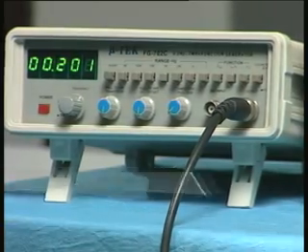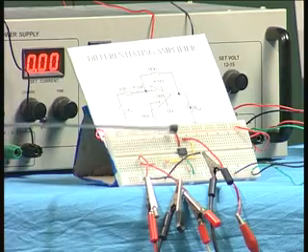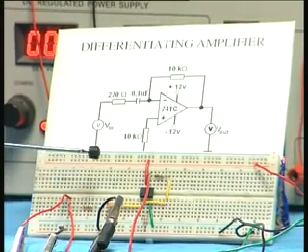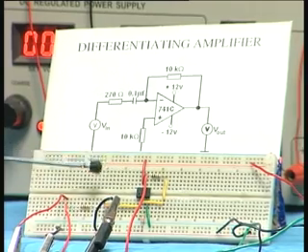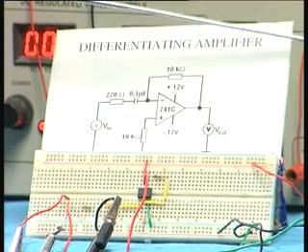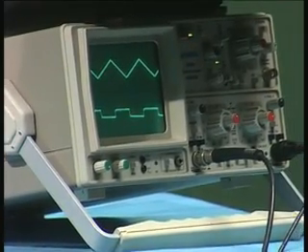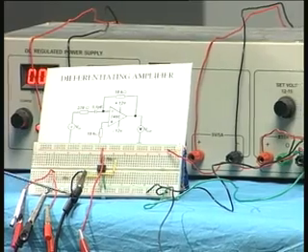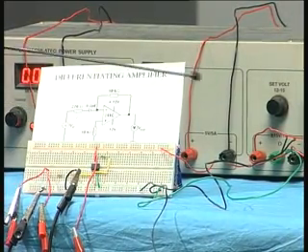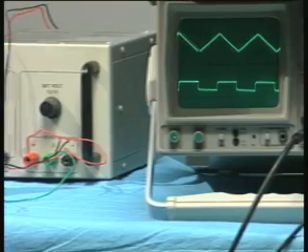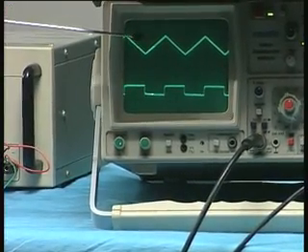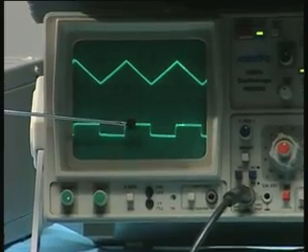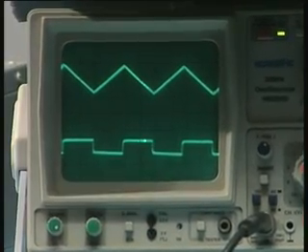So this is the input to this circuit, which is also wired here. You have the same op amp, and the wiring is exactly similar to what I showed in the simulation also. Now this is a dual supply, and the plus and minus voltages are applied along the rail sockets, and then the output is monitored. Both the input and the output are monitored in the oscilloscope, and you can see that I have got a triangular wave at the top, which is the input, and what you see at the bottom is a square wave, which is the differentiated output.